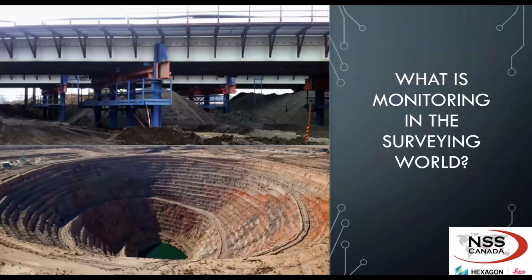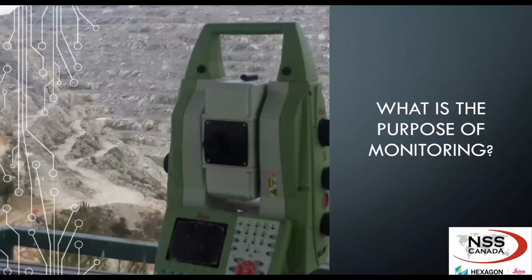So what is monitoring in the surveying world? Monitoring, also referred to as a deformation survey, is the systematic measurement and tracking of the alteration in the shape or dimension of an object as a result of stress induced by applied loads. What is the purpose of monitoring? Deformation monitoring is a major component of recording measured values that may be used for further computation, deformation analysis, predictive maintenance, and alarming. Leica GeoMoS Monitor's main goal is to identify, analyze, and anticipate risks that could pose a threat to the project at hand or the people working within the project.